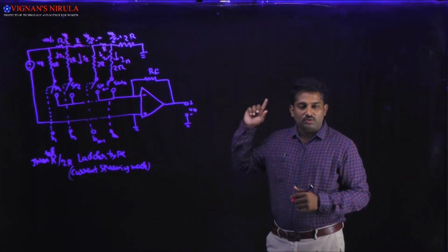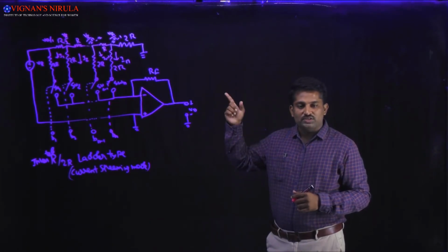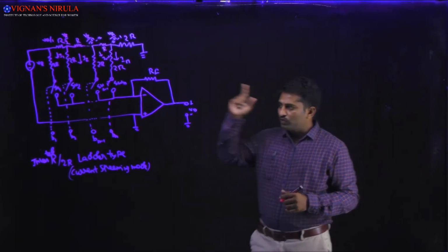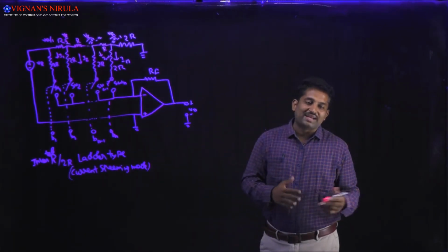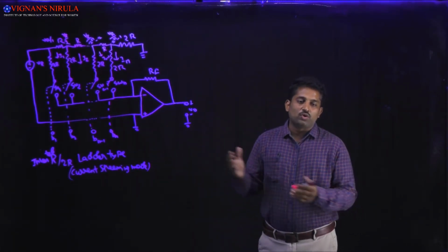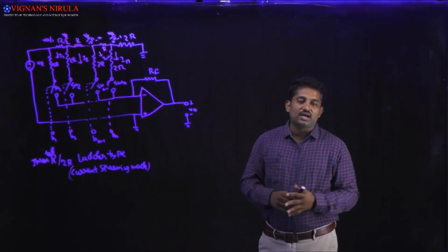There the reference voltage is constant and the resistors are scaling. Here the resistances are identical and the voltage is scaling at the nodes.